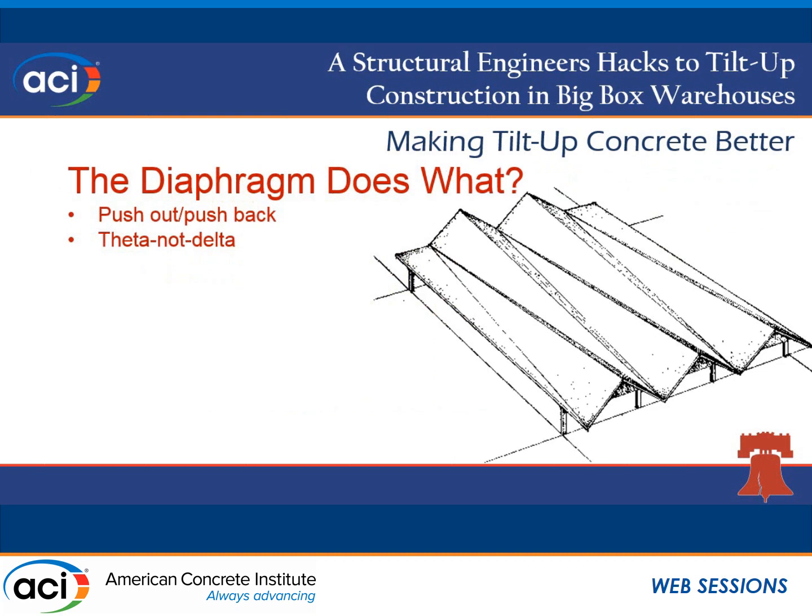Diaphragms, pretty straightforward stuff, but in dealing with your panel design, if you're assuming a fixed base, and I will tell you don't, but if you're assuming a fixed base, you have to deal with what that diaphragm is going to do to your panel, both in terms of what the diaphragm is going to push on your panel. So you have forces that are coming from the diaphragm, not the other way around, which is usually how we deal with out-of-plane forces.